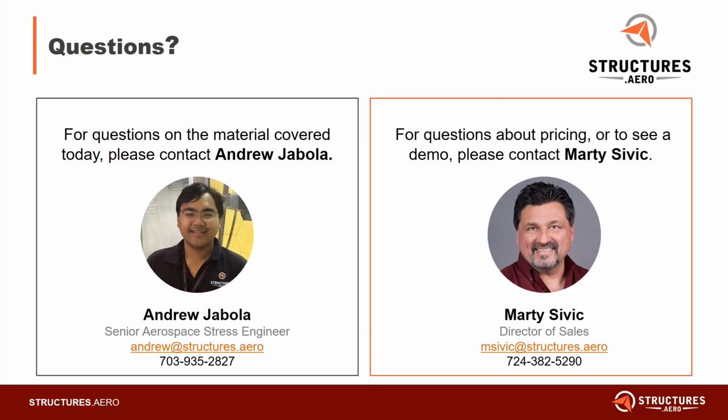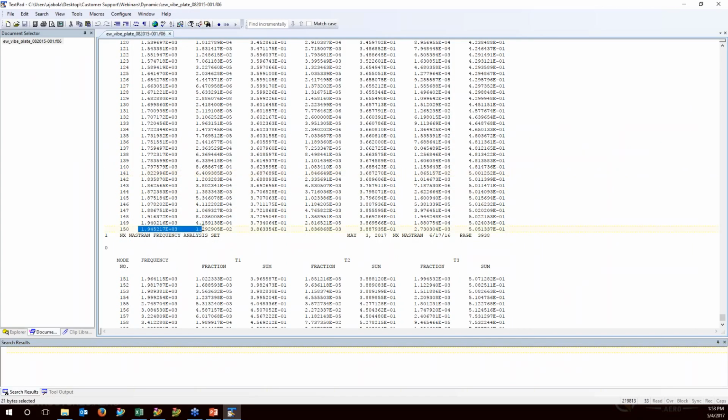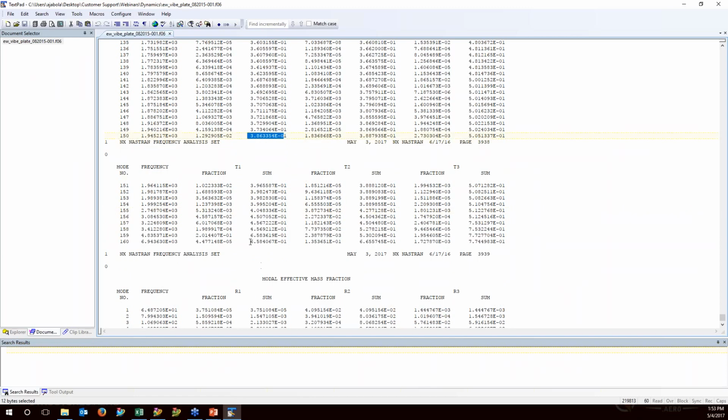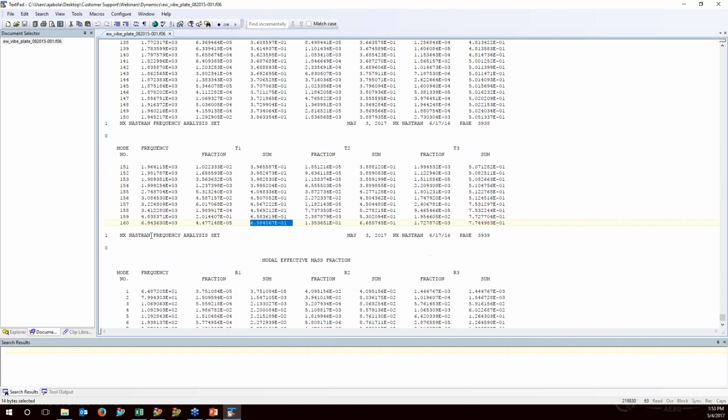All right, so one of the questions that came up was, can you show more detail on the 80% mass participation rate? Again, I had shown only the first 20 modes, and I was looking through my analysis deck and noticed that even for the modes up to a frequency of 2,000 hertz, we're only capturing about 65%. So in this case, perhaps I may actually go back and run this to an even higher level.